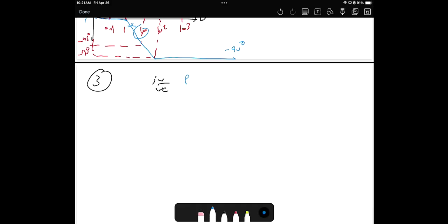This is still a zero, but with no 1, where there's no real part. So what's the effect of it? It is linear with a slope of 20 dB.